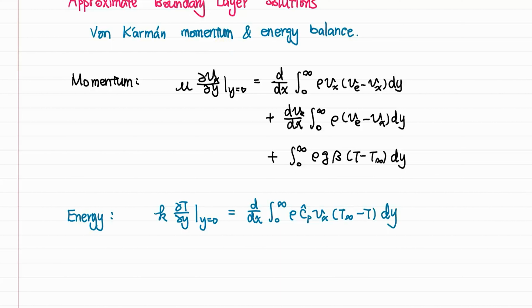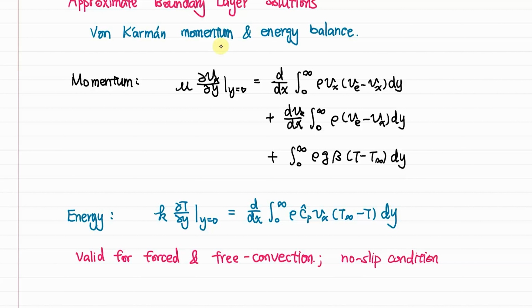Okay, so the von Karman momentum and energy balance, these equations are valid for forced and free convection, and also the no slip condition always applies at y equals 0.